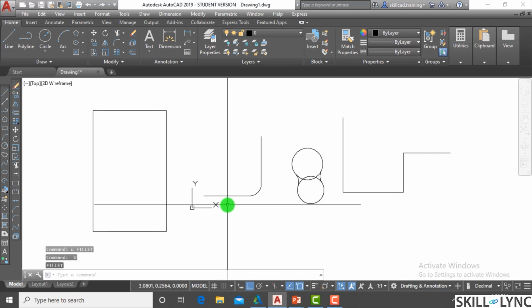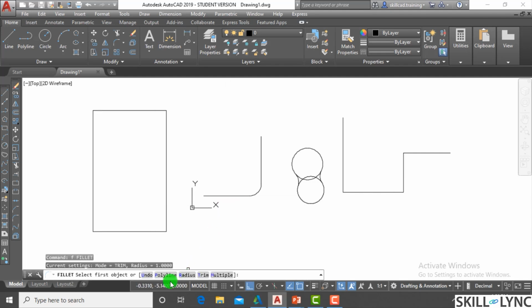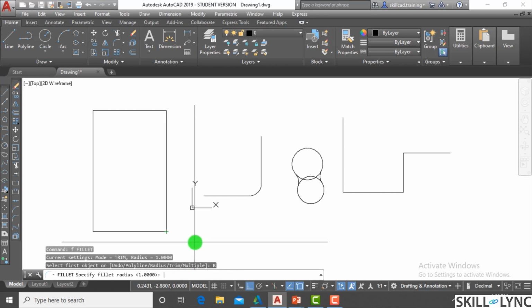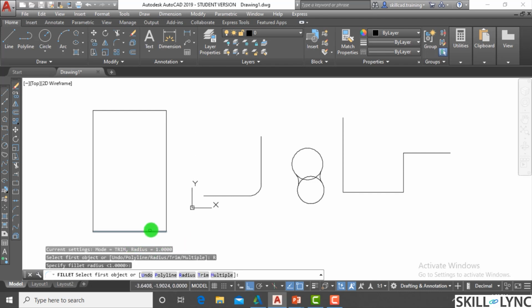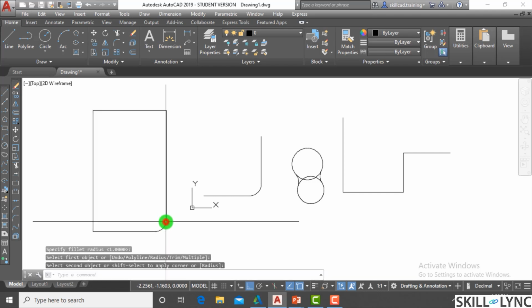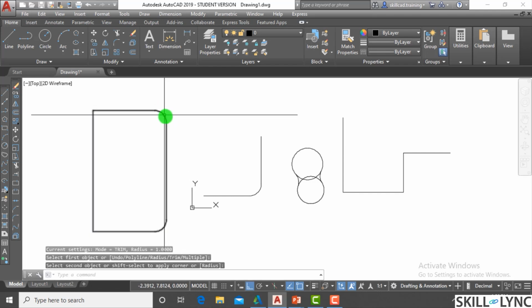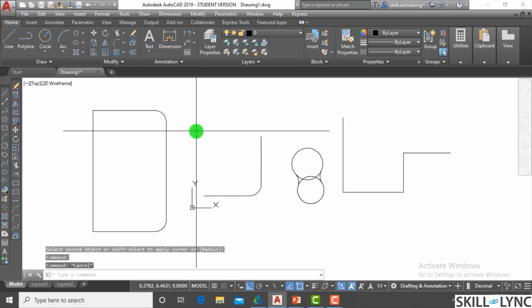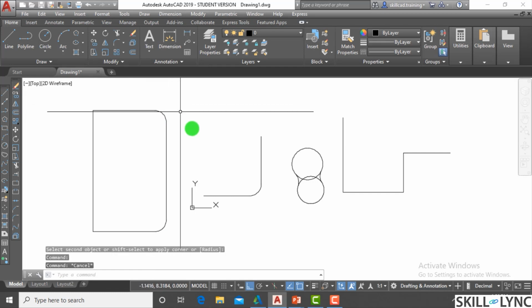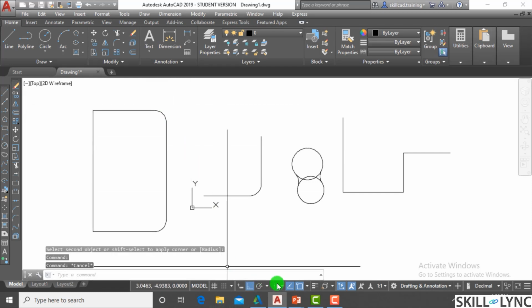But if you don't take the polyline option of the fillet, AutoCAD gives you a provision of filleting the corners, individual corners that you wish to do. Okay, that is all corners. Since it will remain a polyline, but it gives you an independency of filleting the corners.